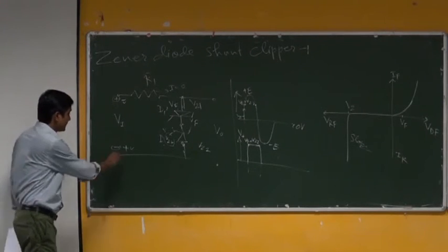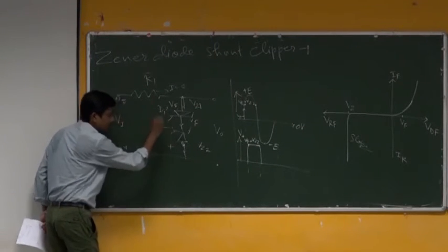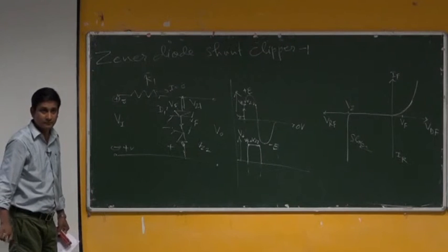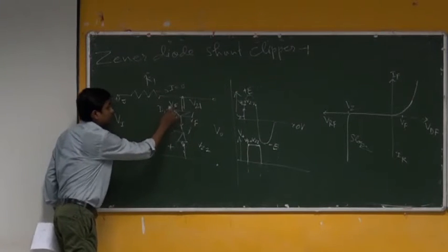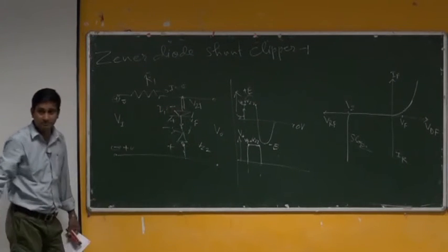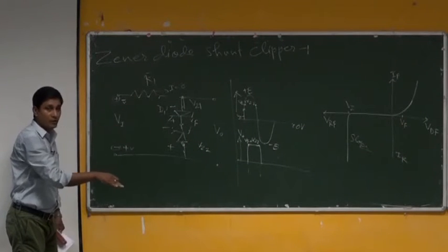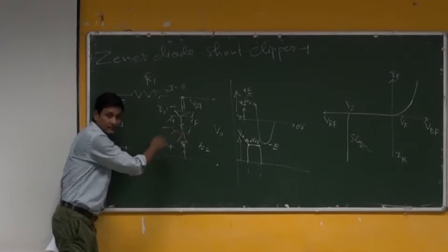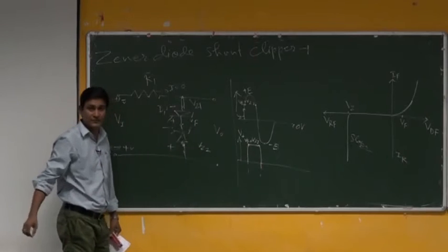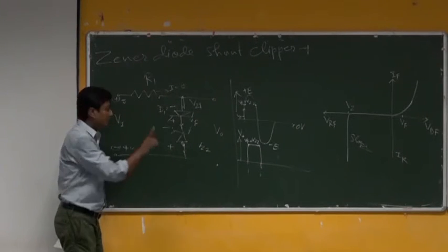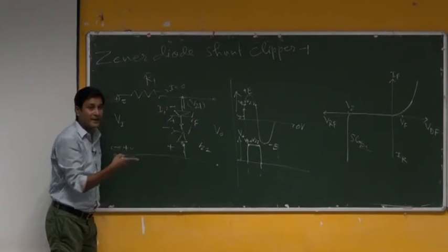Now, I will see there, since this is positive, this is negative. So, my potentials will come here positive, negative here. Since it is connected to the P, positive side, again this will be positive, this will be negative. Now, if it is below Vf of this, it will be tracking the input wave shape till when? Till Vz1, so that this diode gets breakdown.